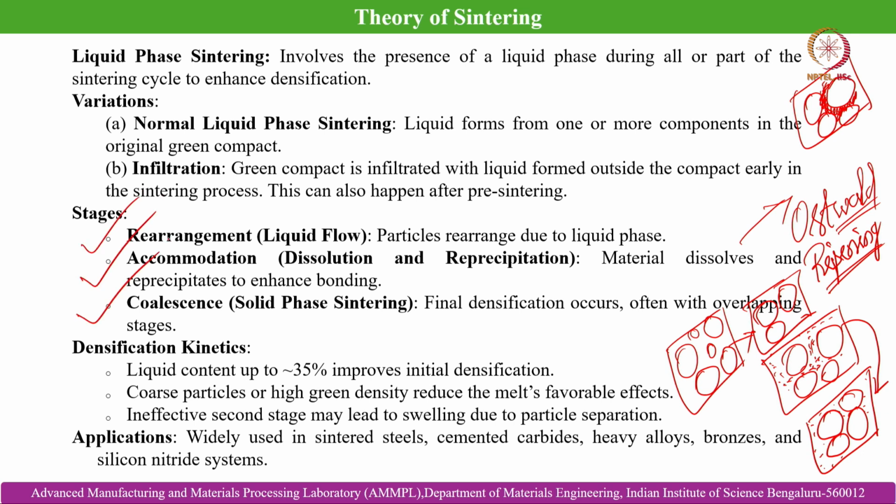and then the final solid state sintering stage, which we have also discussed earlier. So, for your understanding I am discussing again, where the contact points establish the contact, because even in case of liquid phase sintering, the final stage is solid state sintering only. So, where coalescence prevails, because of coalescence only we see the neck growth and also formation of grains in the powder aggregate undergoing sintering. So, these are the stages.